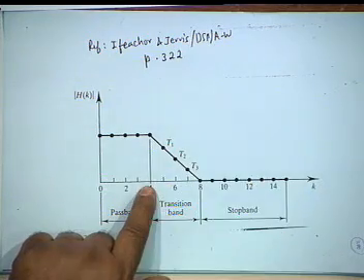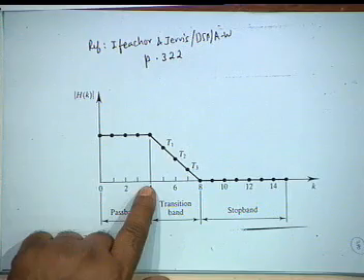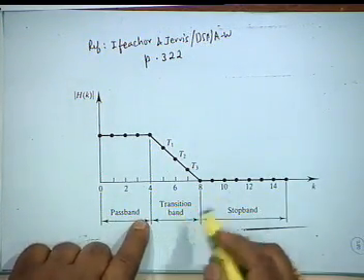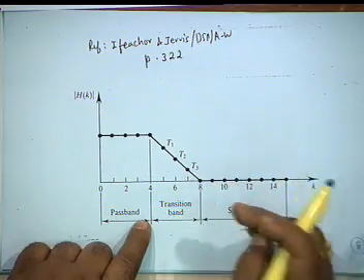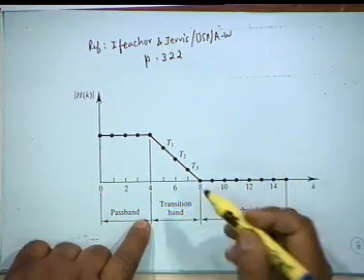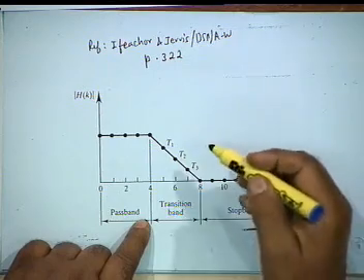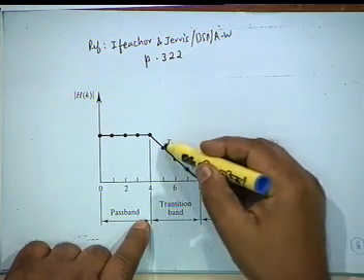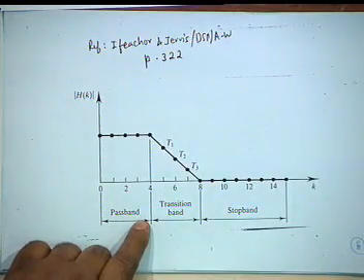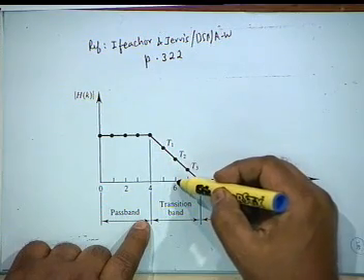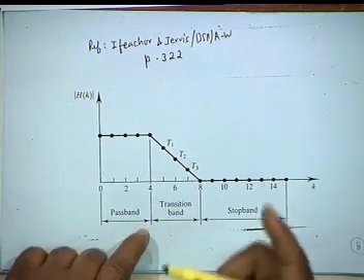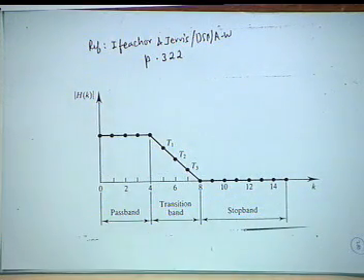Suppose this is the required design, then we can intentionally taper it. That is, between the pass band and the stop band, you can allow a transition band which for simplicity has been taken to be linear, okay, and you can include as many samples as you like. This tapering can be from like this, all like this, okay. You can include 1 sample, 2 samples or 3 samples or whatever number you want.